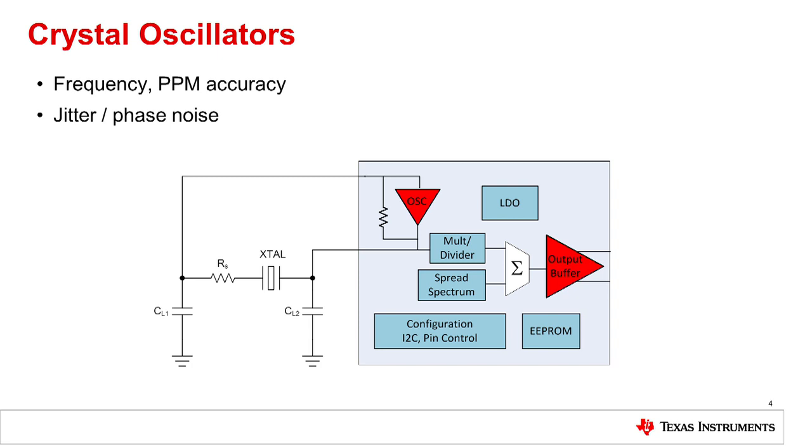Due to the high mechanical resonance, or Q, of the crystal, only specific frequency is allowed to oscillate depending on the cut of the crystal. Typically, this will be in the frequency range less than 100 MHz, with most common fundamental resonances less than 40 MHz or so. The loading capacitance, CL1 and CL2, are used to control the initial frequency accuracy of the crystal. The output type can be single-ended or differential.